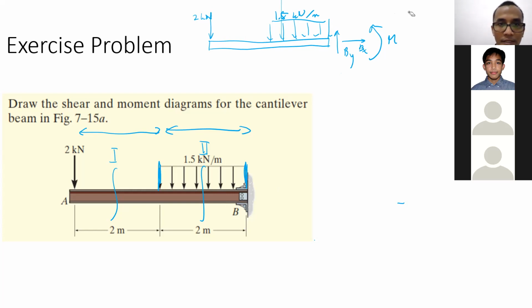But in order to solve this, as I told you before, we are solving for the external force, right? What we supposed to do with the distributed force 1.5 kilonewton per meter? You have to represent the distributed force with concentrated force.